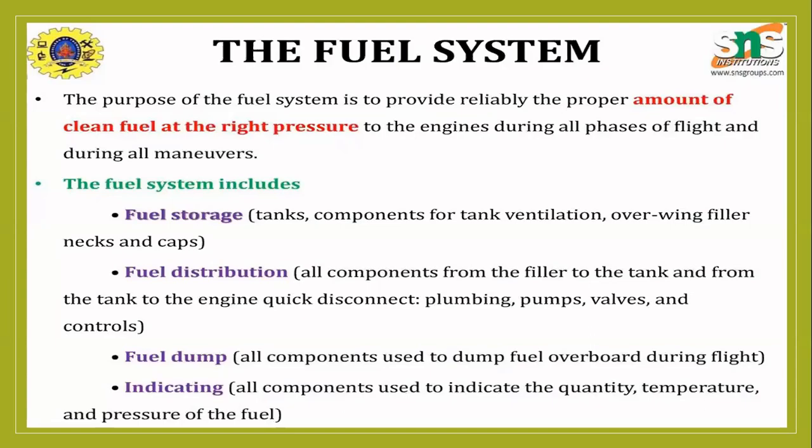When the petrol or diesel goes down, a vacuum is produced above it. If the ventilation holes are not there, the vacuum will pull the tank inward, meaning it will sink. Clearly you understand? The tank will lose its shape.